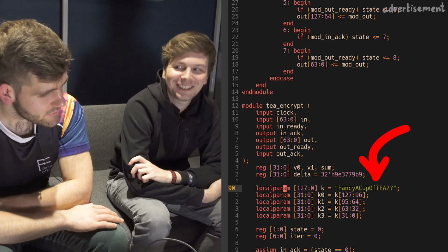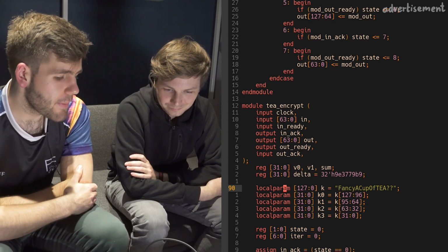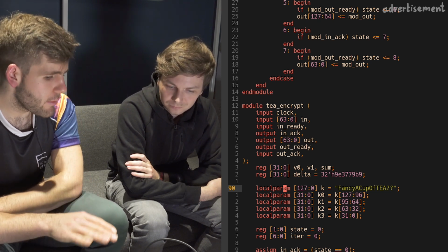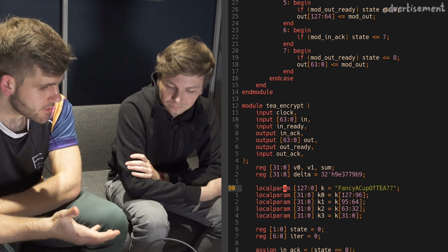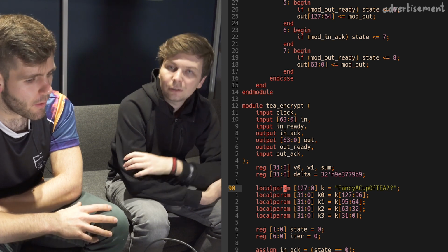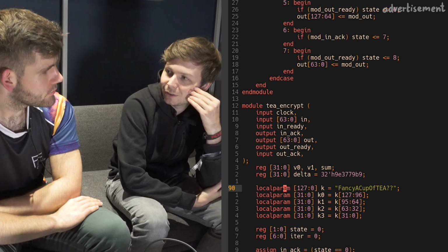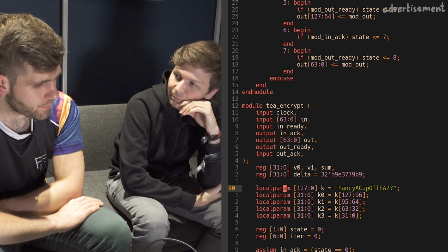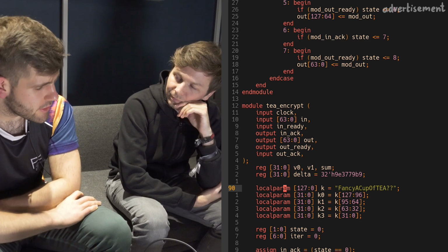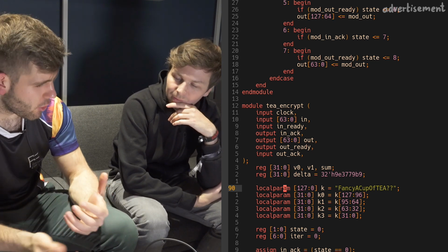Is that the key? That is the key for the encryption algorithm, which, if a team is paying attention and is good at bitstream reversing, they should be able to figure out that there is this ASCII key being used, because this code isn't very well optimized. Gynvael told me he tried to find the key somewhere, but he couldn't find it at all. Do you believe it should be recognizable in the compiled bitstream? It might not be very easily recognizable, but it should be. There will be constants used, and that may be hidden as LUT programming. So it may not be immediately obvious.